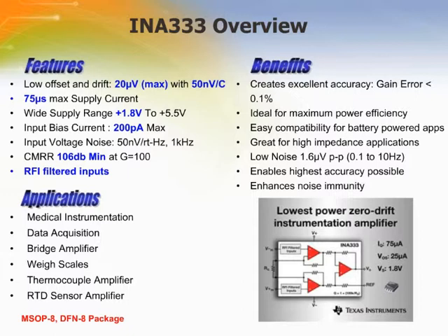Designed with TI's zero-drift technology, the INA333 low-offset drift combination makes it ideal for applications requiring the best long-term stability achievable. And with a proprietary design technique to attenuate chopping noise, the INA333 also achieves industry-leading noise performance in the low power, low offset instrumentation amplifier submarket.